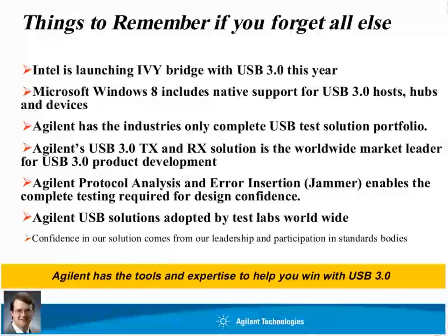The question is: compared with the protocol analyzer, what's the limitation of scope analog capture plus USB decoding and protocol display? You have to remember a real-time scope is sampling for USB 3 at 40 gigasamples per second. So we may have a 1 gig or 2 gig record on a scope, but that's at a very high sample rate.